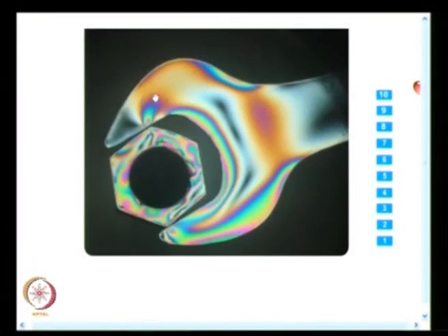Okay. And what you have here is stress concentration, this is the load contact point, and you have stress concentration here, and you have the fringes developed on the edges, and you have seen very clearly that all these colors have emerged as a function of what you have applied as load.